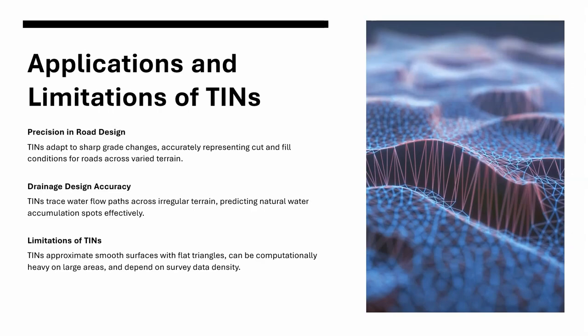There are also large area inefficiencies. For regional mapping, say an entire county, TINs become computationally heavy. Thousands of points generate tens of thousands of triangles. For broad areas, a grid-based DEM might be more efficient and realistic to work with.